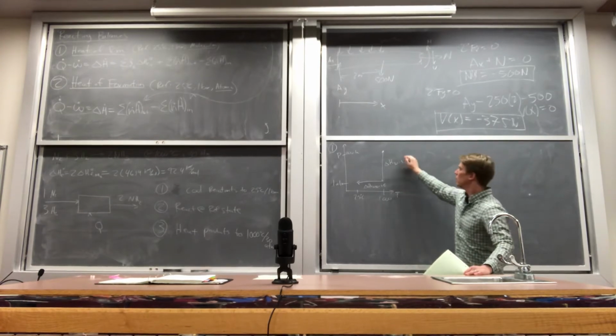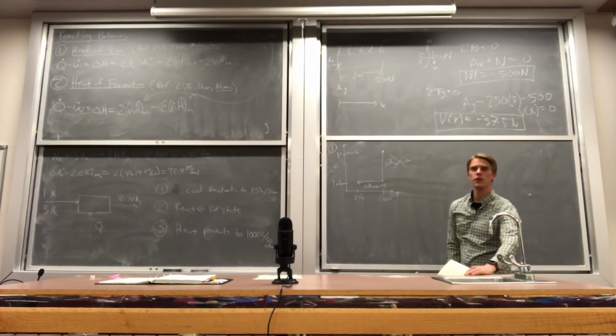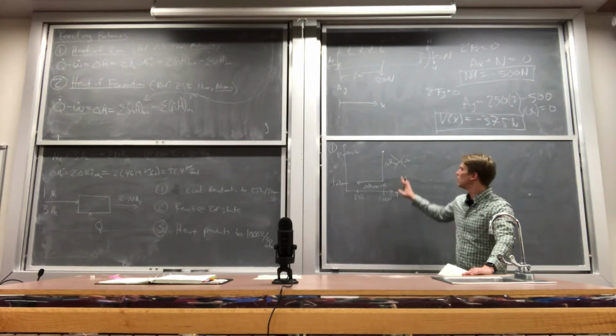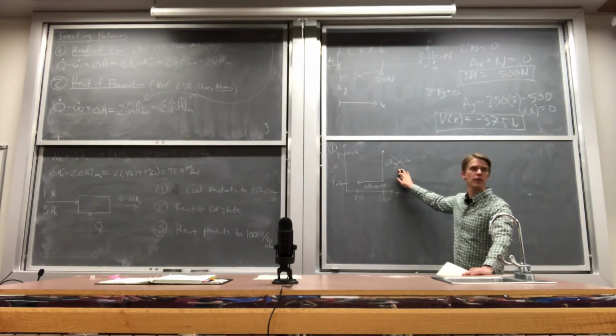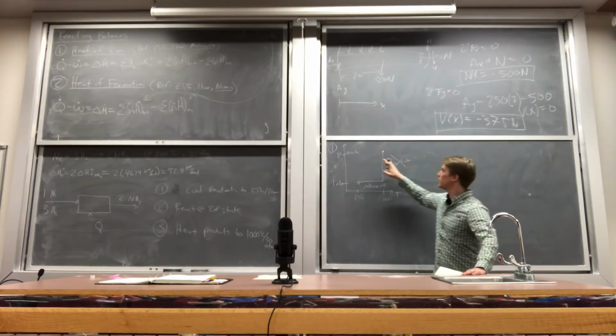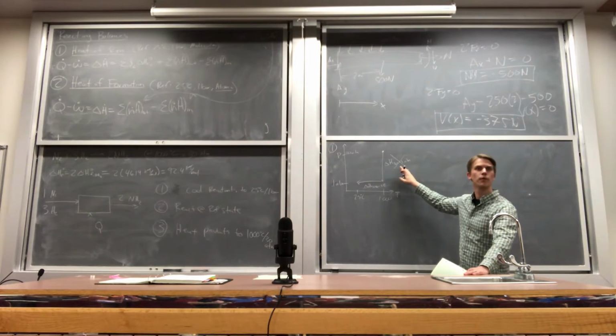For this one here, if we assume it's an ideal gas, this is actually 0. Right? The enthalpy is not a function of pressure for an ideal gas. For a real fluid at 30 atmospheres, this is not going to be 0. But for the purpose of what we're working on, we're going to neglect this contribution.